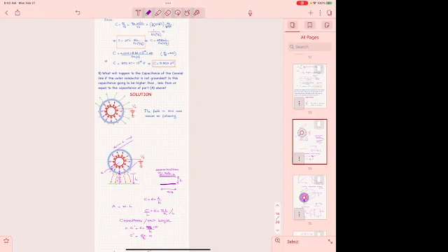This is the probe station. When they press, if your probe is misaligned, if somebody pushed it so hard in a previous experiment that one ground looks like this and does not contact well, then you lose your ground there. That's one problem.